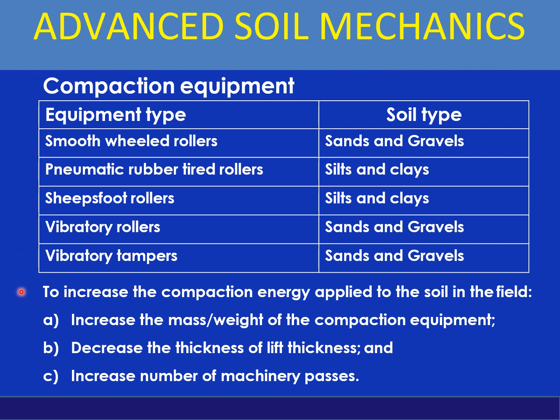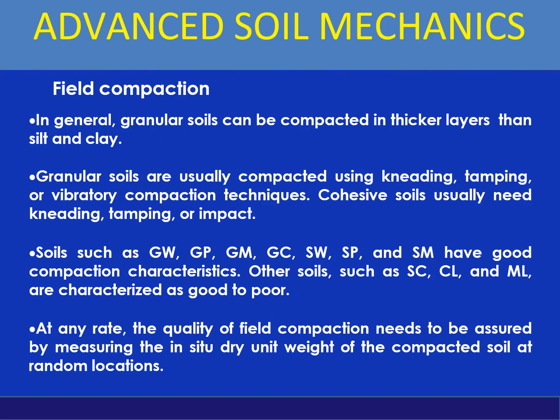To increase the compaction energy applied to the soil in the field, increase the mass or weight of the compaction equipment, decrease the lift thickness, and increase the number of machinery passes. Field compaction.